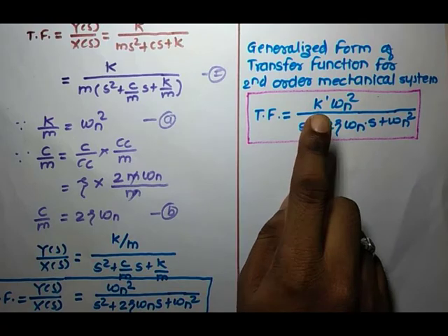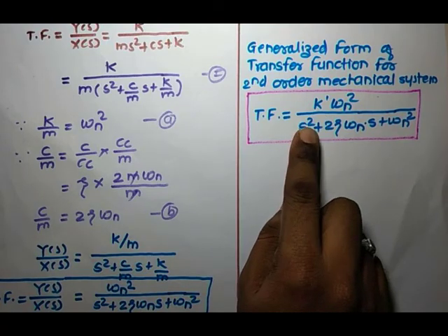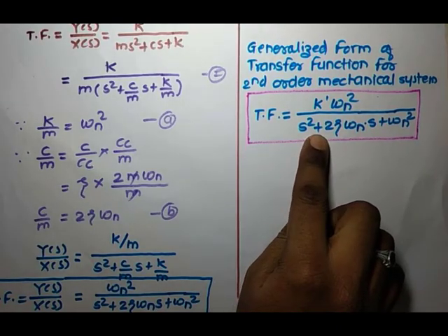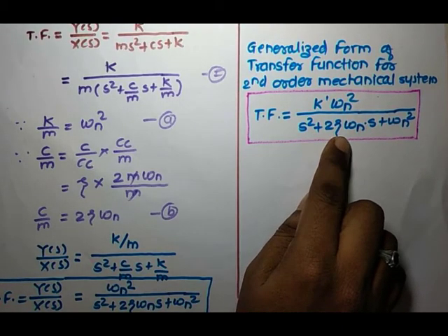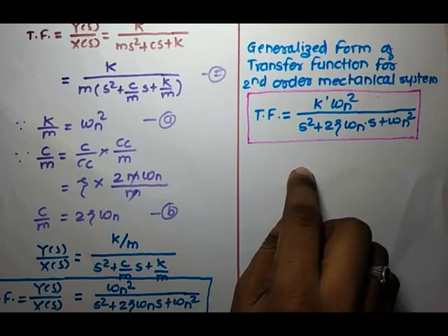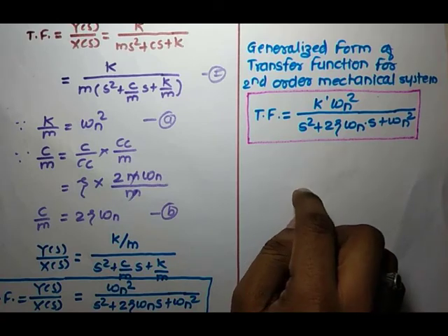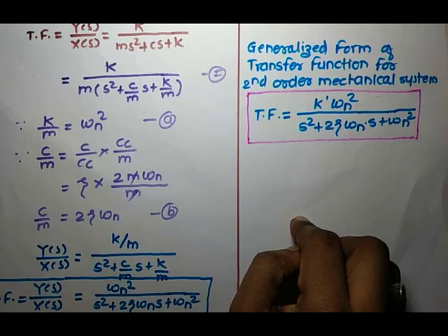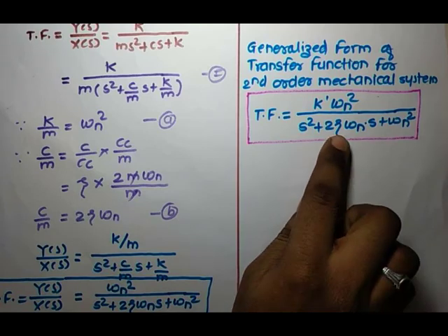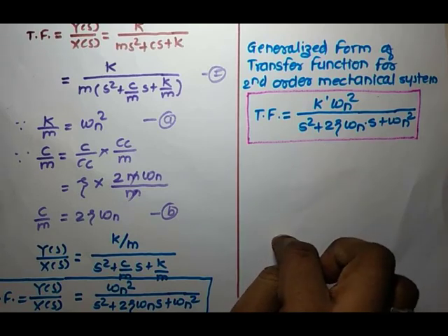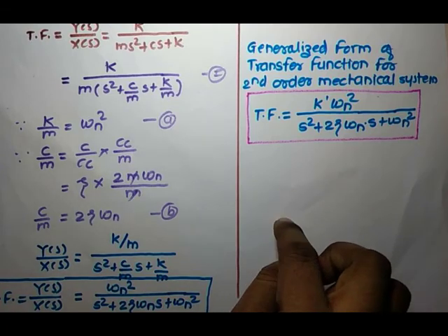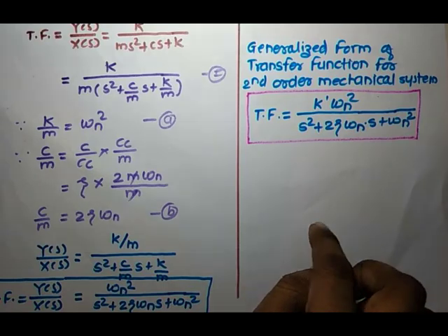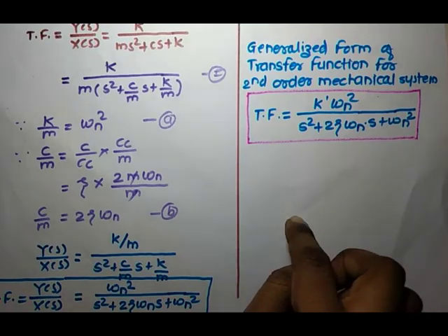So we'll use this transfer function to solve a numerical, and we have derived the equation that we discussed before starting this session. So we'll find the roots of the characteristic equation, and based on these roots we'll have three different systems: overdamped system, underdamped system and critically damped system, and we'll try to understand the importance of zeta while defining these three types of system. Out of these, the underdamped system possesses some oscillation, and that will be the case of study, since the oscillations are still present in that system, but still we are expecting the system response to be as fast as possible.